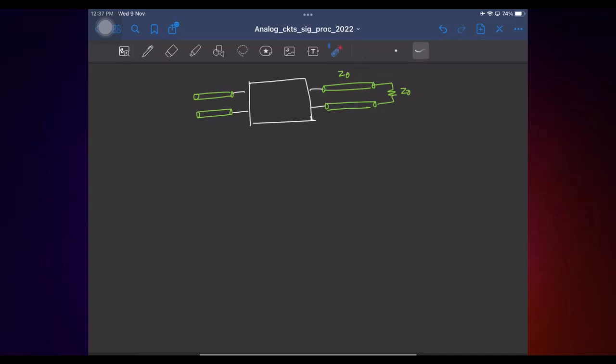No, I mean, this is under your control, right? See, this 2-port network is something you design. You are going to put the cable. What you are going to do here is under your control. So at least it makes sense that if I put Z0, no reflection comes. Fine. Similarly, at this end also you put a source Z0. But what I was saying is that there will be some ZL fixed at some other end, because eventually we have to deliver power.